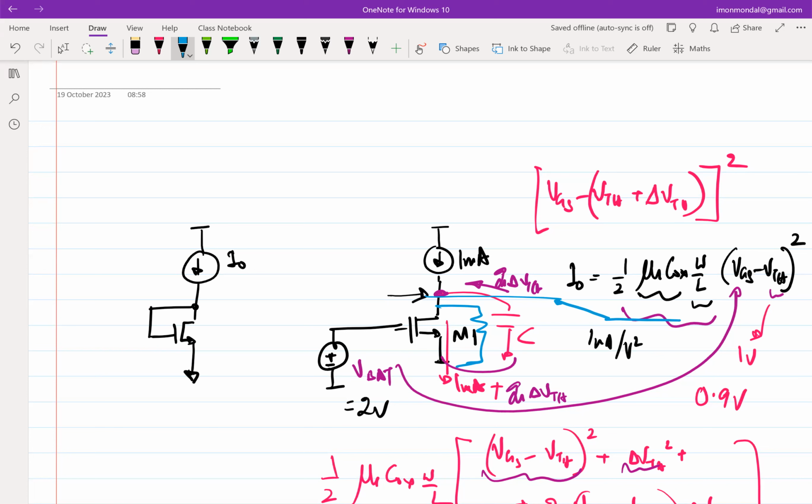In a circuit, the independent variable is the VGS, and the dependent variable is the current. But if I have to fix the current, we are trying to make the current the independent variable, which means I have to make VGS the dependent variable on the current. You cannot have two different independent variables trying to set the same output. That's the main problem.